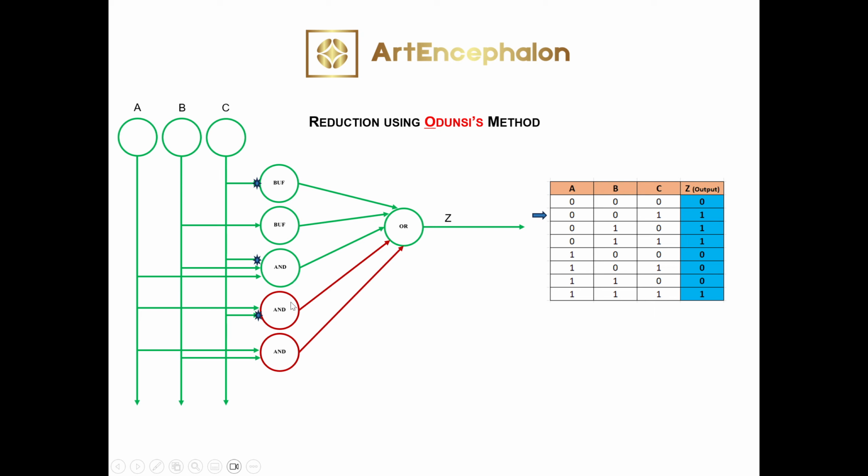The second AND gate, if you look carefully, is an inhibitory neuron. It is a 2-input AND gate, so you need 2 inputs for this AND gate to fire. Clearly, looking at this, none of the 2 AND gates would fire. Only the buffer neuron will fire. So when we progress this, we see that none of those 2 AND gates will fire. Only the buffer will generate an action potential that will travel all the way down to the receiving Z neuron